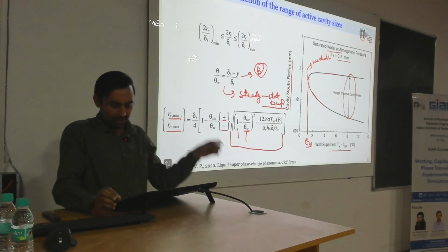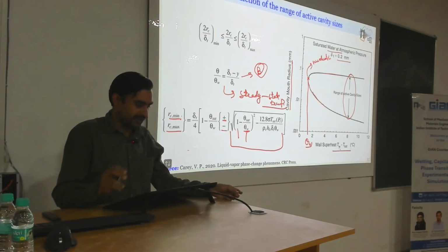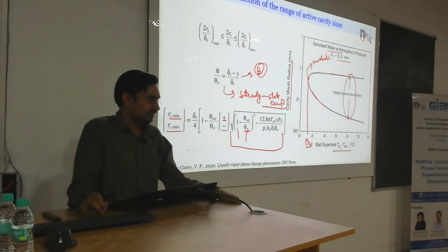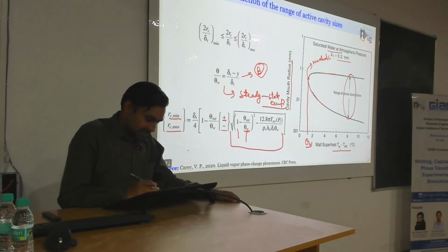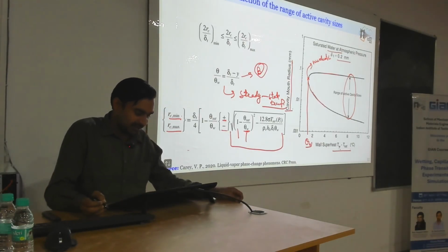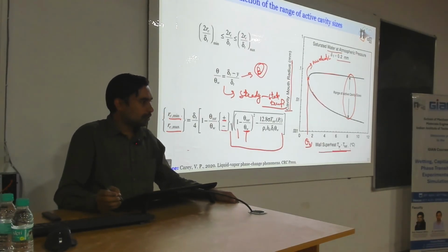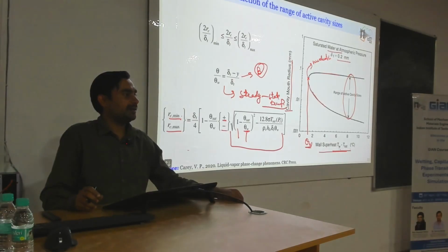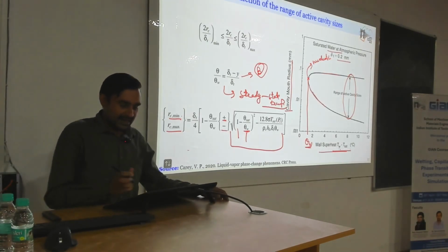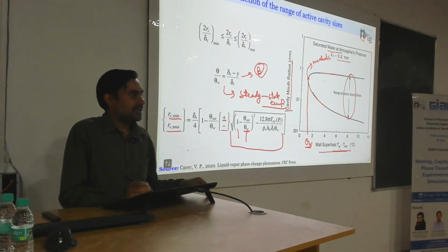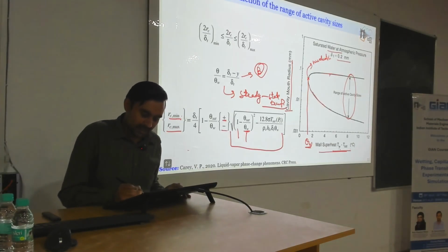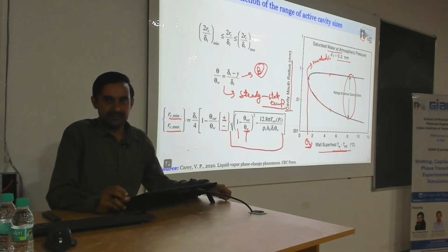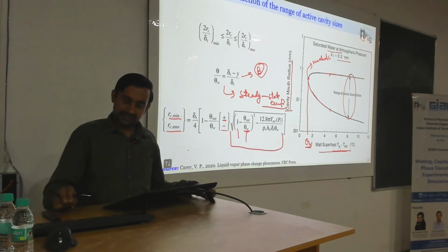We started our discussion on nucleation from cavities and onset of nucleate boiling in the previous session, and part of which is left that we will now be continuing. If you recall, this was the last curve where we left. We had cavity mouth radius as a function of the wall superheat, and we found that a minimum amount of wall superheat is required for the cavity to be active. As we increase the wall superheat, we find a spectrum between the minimum and maximum value of the cavity mouth radius, which will be acting as the active nucleation sites.